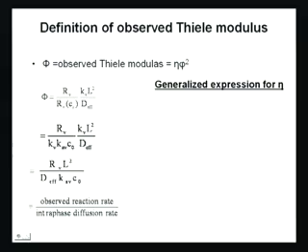Shape normalization, right. For different shapes you can come up with the same expression, and as I said before, the expression that we are going to use is not going to be completely accurate for all shapes, but it is going to be very close. There is going to be 5-10% error maybe, but even with that you are pretty close. In shape normalization you cannot have 100% accuracy. So the expression that we are going to use is eta equals tanh phi over phi.